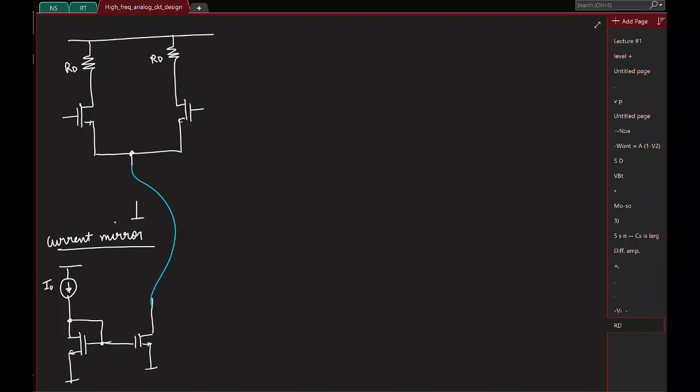So now we have a complete transistor level implementation. What is the output impedance of this guy if I call the transistor M1 and M0? R0 of the transistor, that's all. Because incrementally the gate is at ground. If you make any changes to the drain, no change will be reflected at the gate. So gate is at ground, source is at ground incrementally. So the only thing you have in the incremental picture is the R0 of the transistor, and that's what you get.